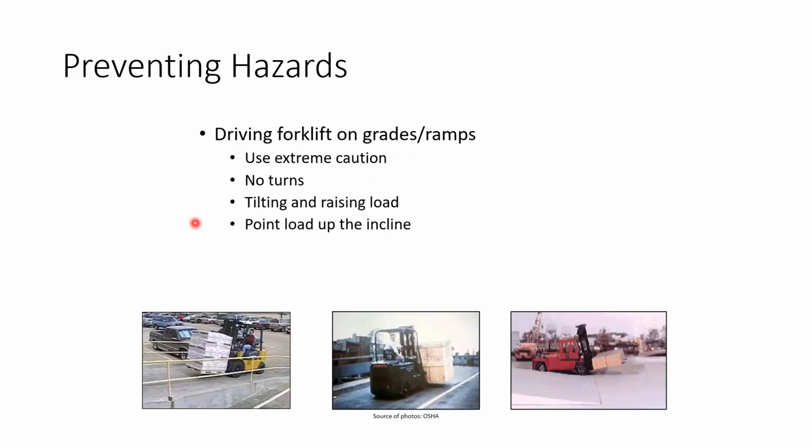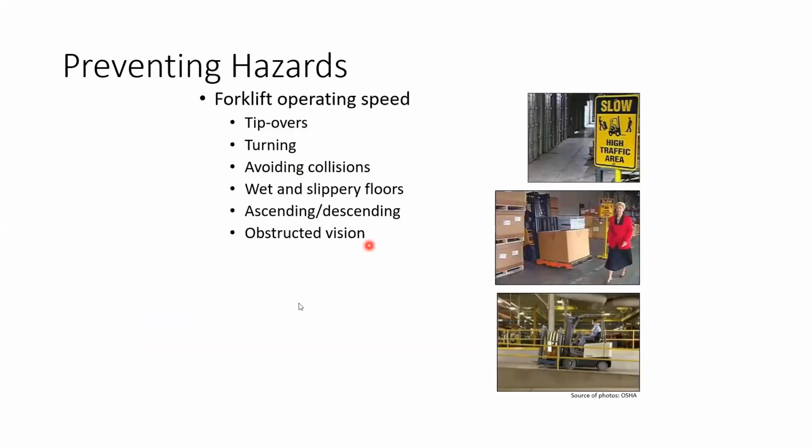Okay, driving forklifts on grades and ramps: use extreme caution, no turns, tilting and raising loads, with the load pointing uphill. All of these are the instructions for how you can prevent these hazards.